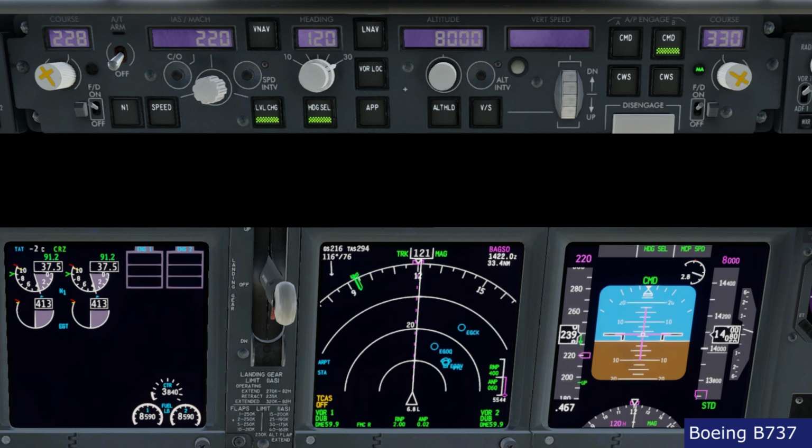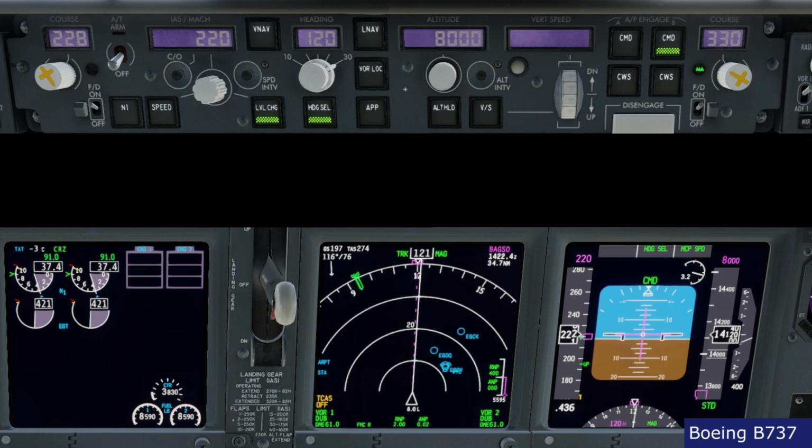Now you will see that we reached 220 knots and we're going to start descending, because of course with 37% we either lose the speed or lose the altitude. Flight level change is a safe mode and will maintain the speed, so you're not going to bring the aircraft to a stall in this case, but we're going to start the descent. You see, we reach the speed and the vertical speed now increases, we start pitching down.